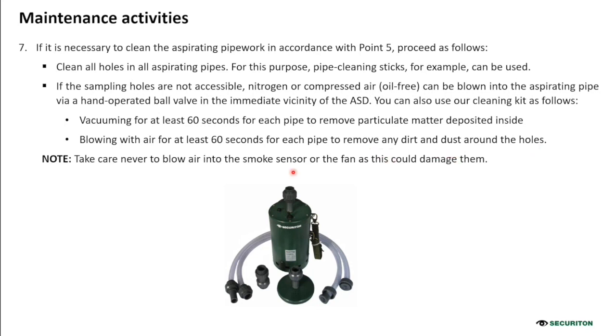So this time is just an indication. You can also make it 2 minutes or 3 minutes. It depends on the ambient conditions. What is important to know when you use this tool or compressed air, you must never blow air into the smoke sensor or the fan because you could damage the detector. So be careful.